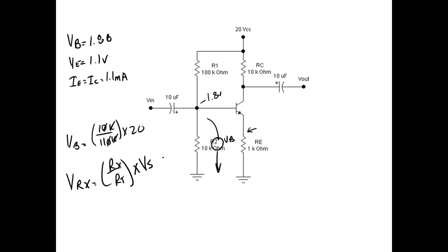And the ratio does not change with whatever voltage you put on there. So this is what I was talking about in DC. We want to calculate the voltage drop across R2, and I start off with 20 volts, and everybody comes up here and calculates RT. They take that and divide that into VS. They calculate current, and then they multiply that by all the resistors.